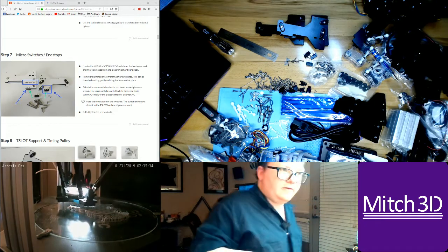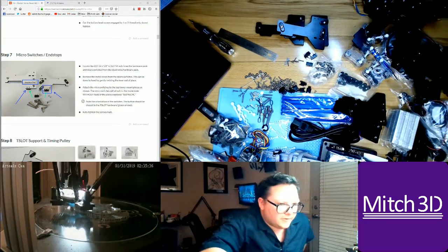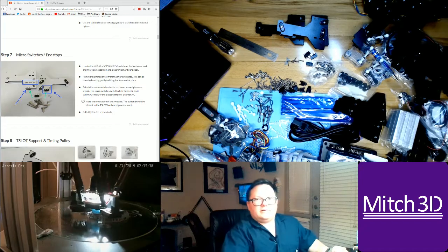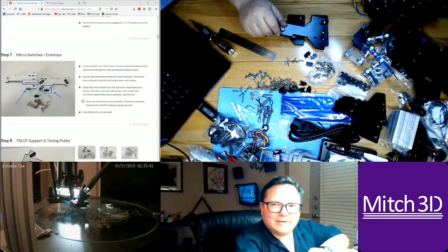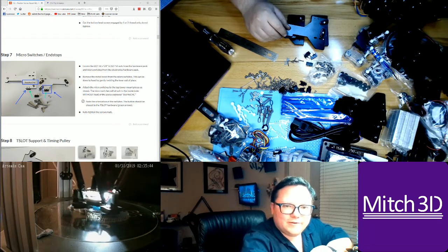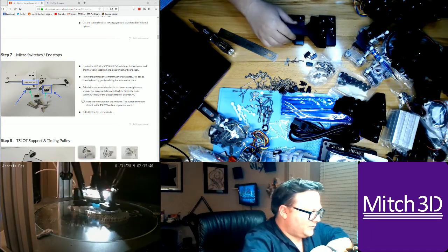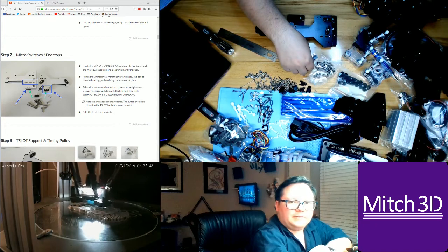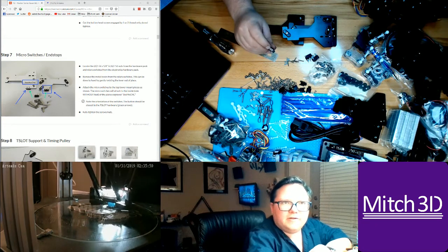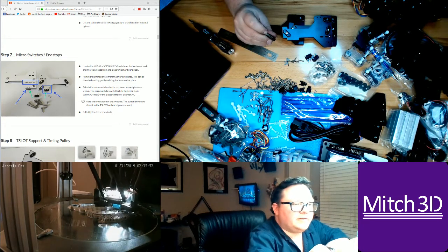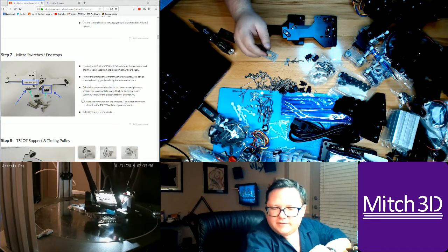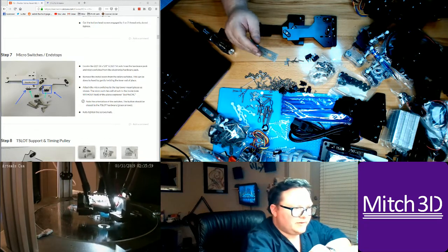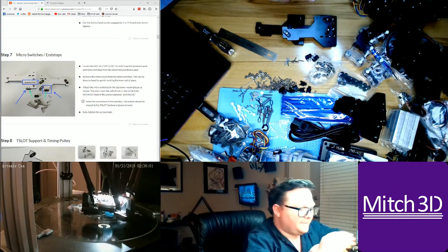So the effector has the auto leveling probe and the hot end, and that's the only real wiring you need. And then the motor is plugged directly into the control board, and it's using a Rambo Mini, which is a Repetier firmware, but can easily be replaced with Marlin, and I probably would do that, but I'm using a Duet.